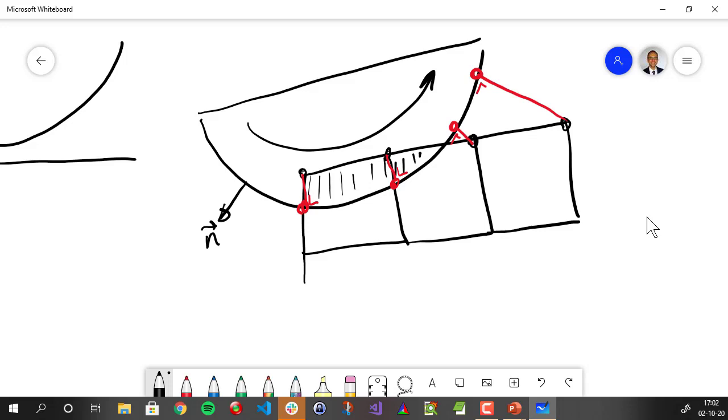So I can say that this gap is negative, this gap is negative, this gap is positive, this gap is positive. And the idea is to create a force. Metafor will create a force which will act on each node that has a negative gap, which is proportional to this gap size.